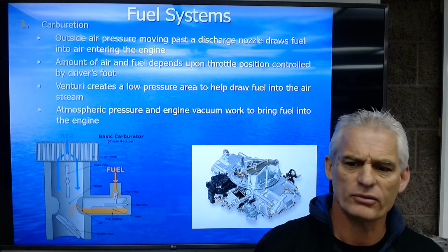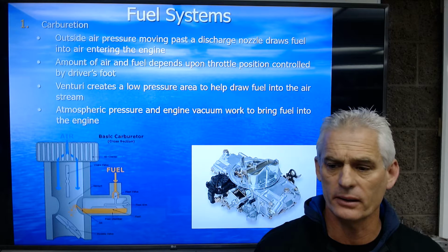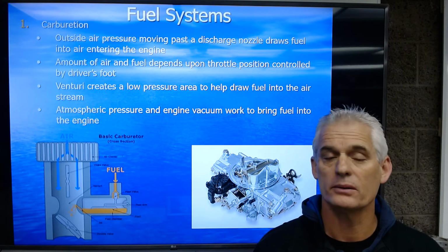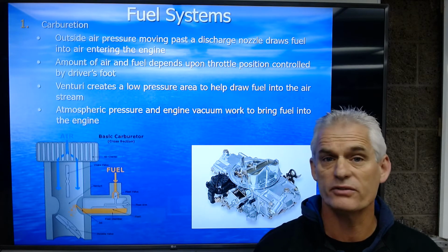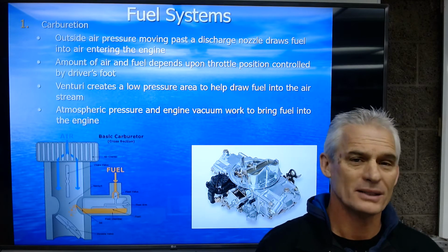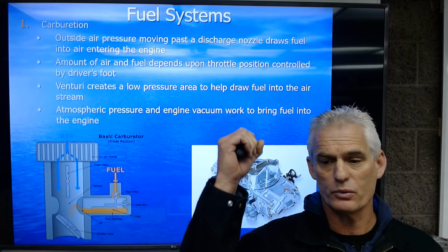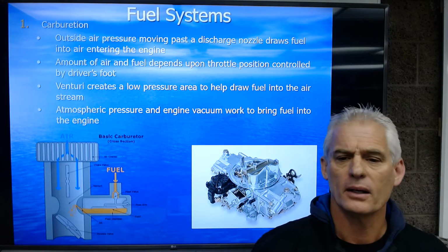But let's step back for a moment and ask, what's the purpose of the fuel system? Well, we have to deliver gasoline and air into the engine, and we're going to compress them inside the cylinder into a very hot and explosive mixture. If we compress gasoline and air together and give it a spark, then we get an explosion which drives the piston down, if I suppose my fist is a piston, and so on.